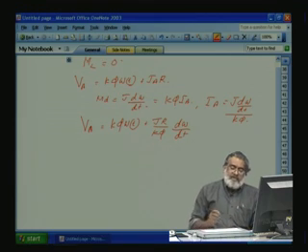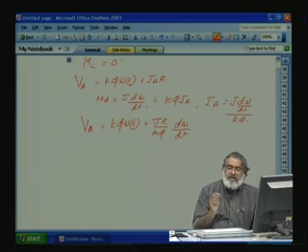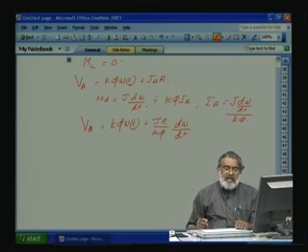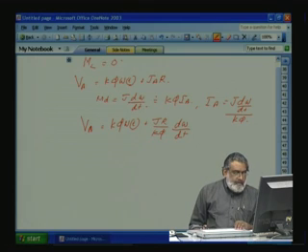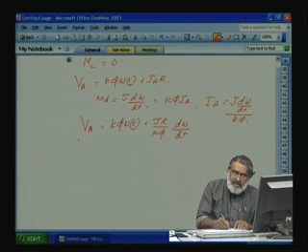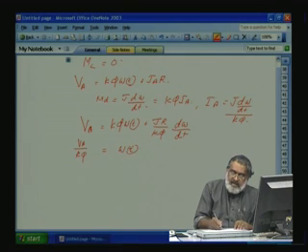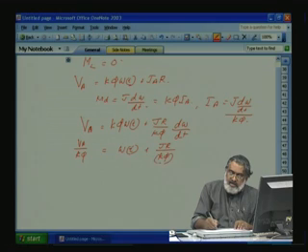Okay. So we are applying the voltage, and leakage inductance we are neglecting, and we are giving nearly constant current. So full driving torque is given, and the machine is accelerating. Okay. Once the speed reaches the full speed, let us divide this one by K phi. Va by K phi is equal to omega t plus JR by K phi square into d omega by dt.